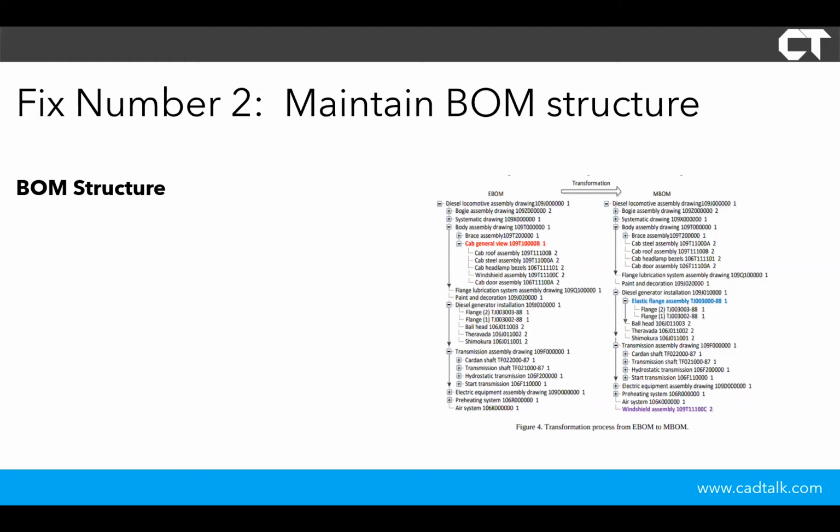And if you think, oh, I want to flatten the bill out, we should really ask ourselves why we're trying to do that. What are we trying to achieve when we do that? Something else that the levels do, the levels give us more details and make it easier for everyone on the shop floor to understand the steps for building the product. Once you have levels and the operations, the steps become more obvious about what parts go into what assemblies. The flatter the bill is, the more you get a big pile of materials or a big pile of parts, and now you have to deal with maybe putting multiple things together. It really adds confusion to the shop floor.